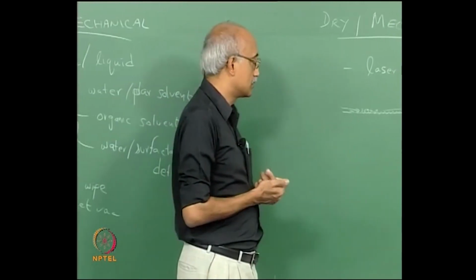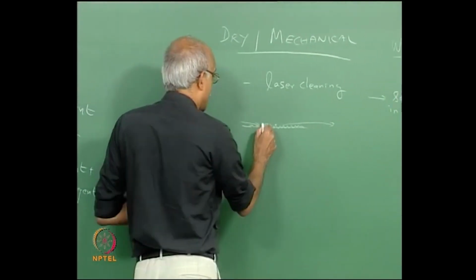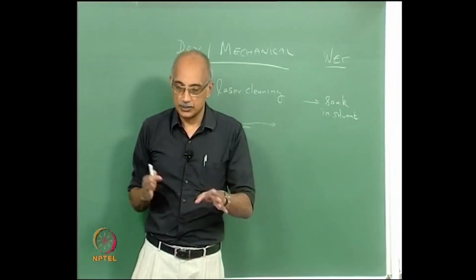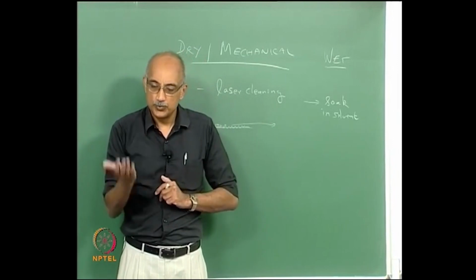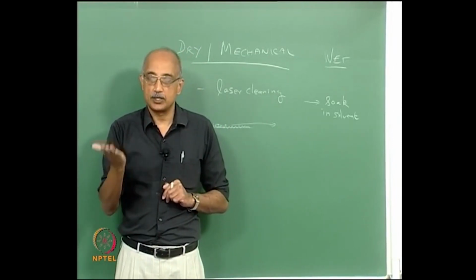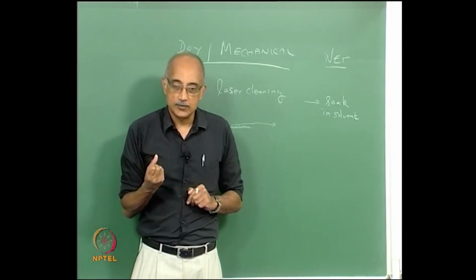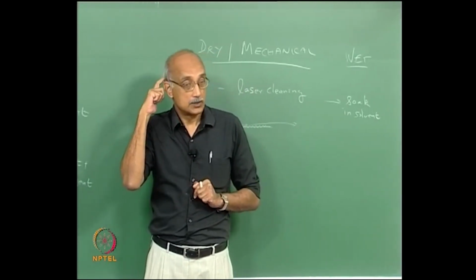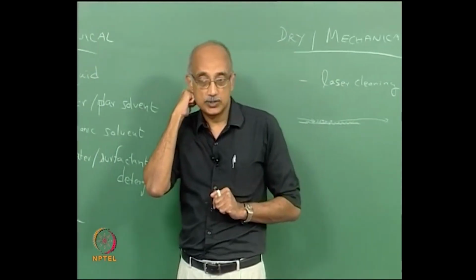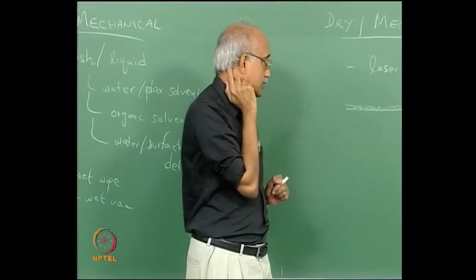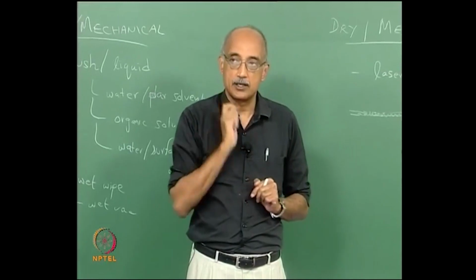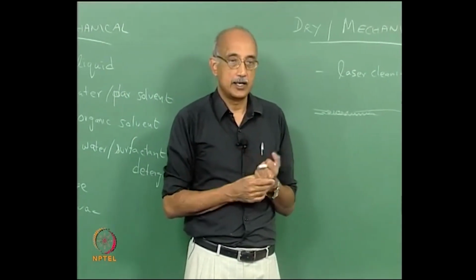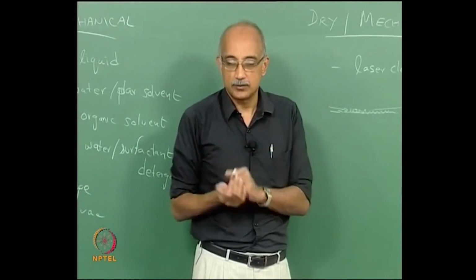It essentially just boils the solvent off the surface. And as it does, once again, the particles that are entrained now in the liquid or the solvent that the surface has been immersed in are removed from the surface, not just by the vibratory action of the surface, but because of this explosive boiling of the solvent that has been placed on the surface. So particle removal efficiency using laser can be enhanced by a factor of 10 or higher simply by pre-soaking the surface in a highly volatile solvent.